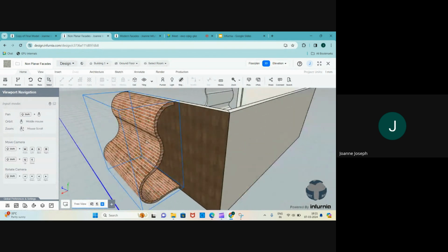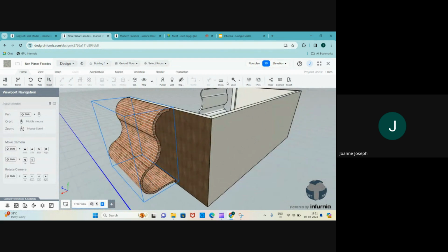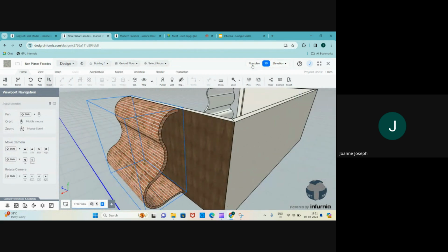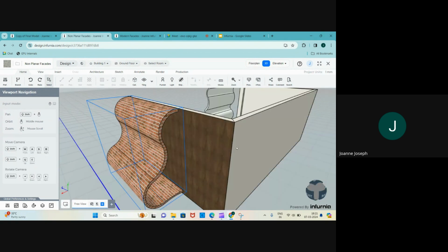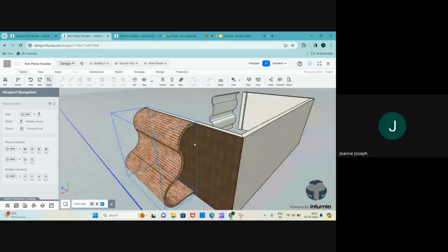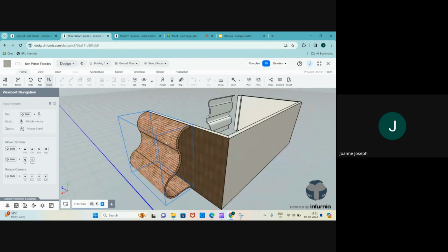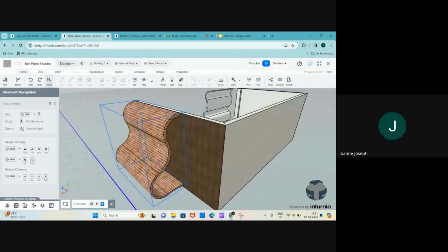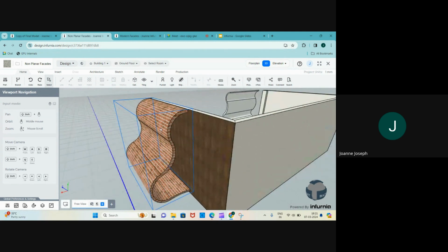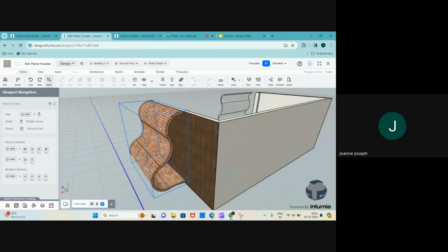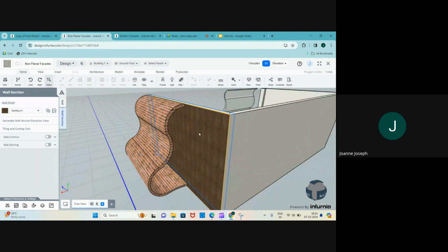And it is simply used by creating another wall, which will not be visible in 3D. The only problem is that it will be visible in your floor plan. But that is actually something you can mask in your presentation drawings by using some other methods as well. So largely speaking, especially for the sake of 3Ds, this is quite a useful tool if you want to create curvilinear kind of protrusions, which you can't really do by clicking on this surface.